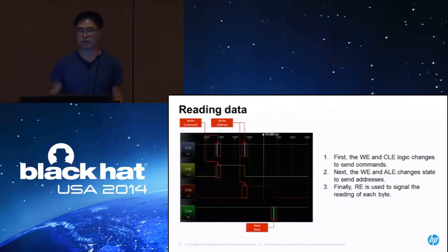And actually, you can verify that yourself using a logic analyzer. You can just put the logic analyzer on each pin and catch the signals, and it will help you to understand the whole operation.